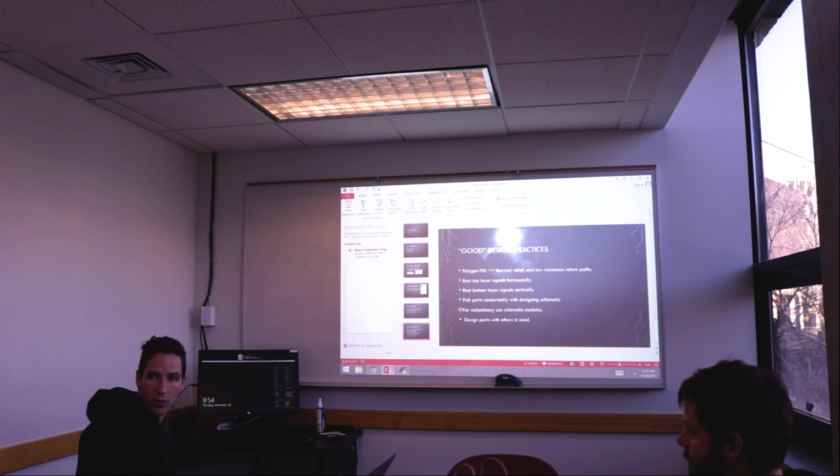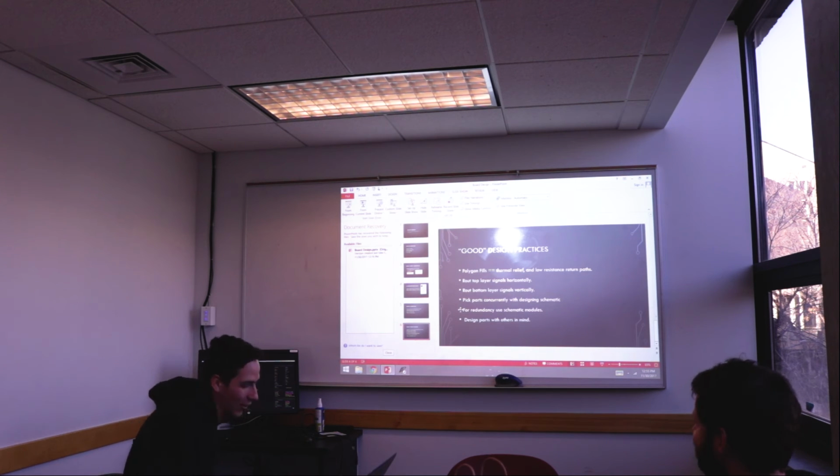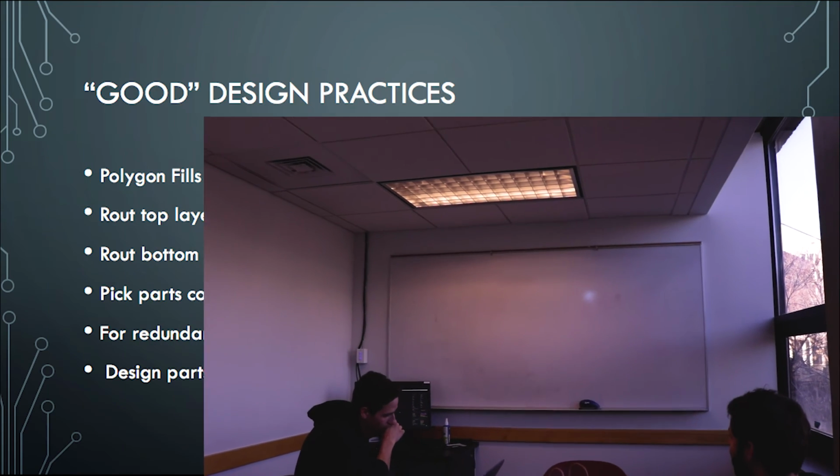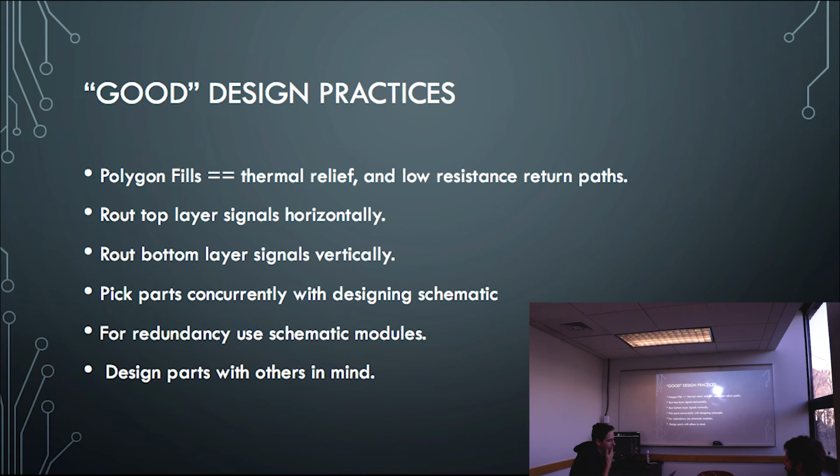You guys know, I guess, what were you taught when routing boards? Was it just like, all right, go at it? Pretty much. All right. So when I'm routing a board, I usually don't use the auto router. I usually just route it by hand. That way when I'm debugging, I know exactly what signals go where, and it's easy to reference.